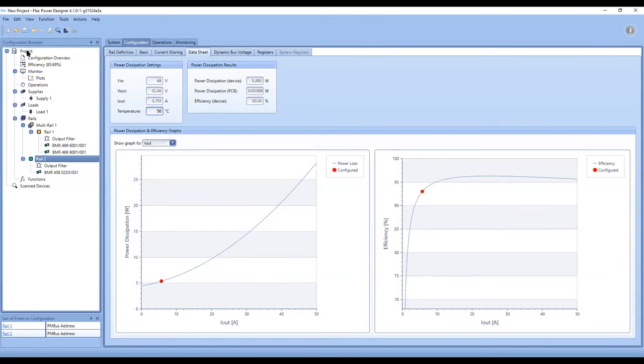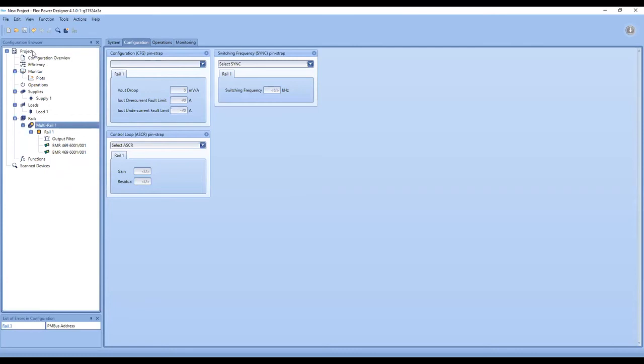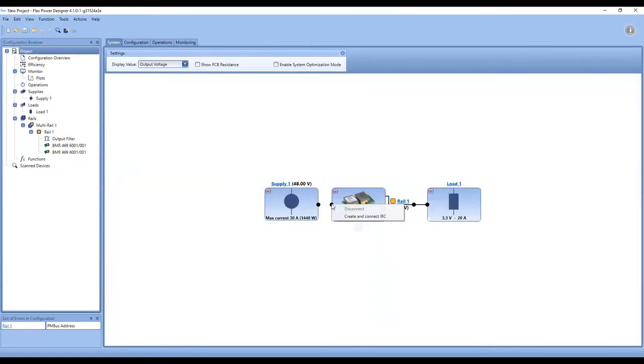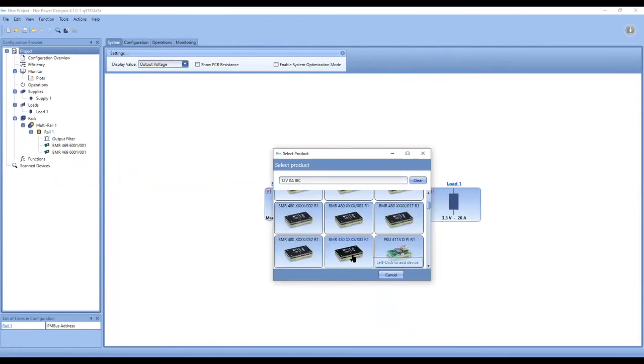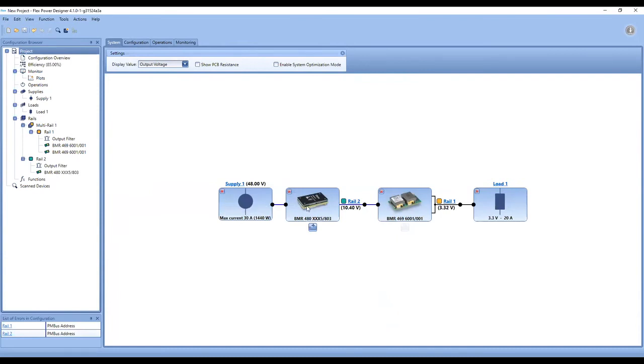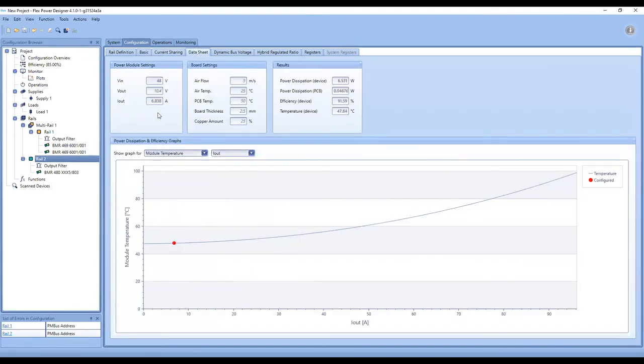However, with our recent additions, if I change the product to something that is a little bit newer, let's do the same procedure again, and I will choose this one. So connect again and back here to the datasheet view. What we can see now is that the temperature has disappeared from the input settings panel and instead ends up as a result. So we now have a thermal model that, based on this input, can calculate the temperature that the module will have under these circumstances.